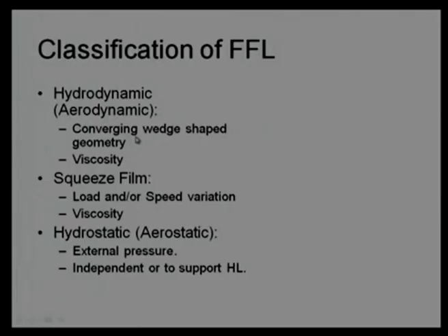Both of these mechanisms require two actions. One is that there should be some viscosity. If viscosity is 0, then it will not occur, or we say solution will not be obtained using conventional equations. Another thing is a converging wedge shape. There should be a convergence, there should be some inclination, there need to be a gradient which makes hydrodynamic or aerodynamic action or mechanism.